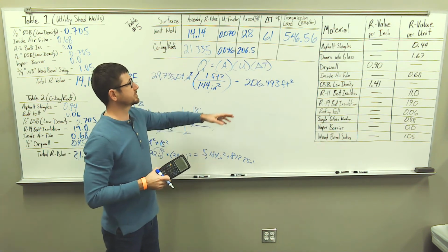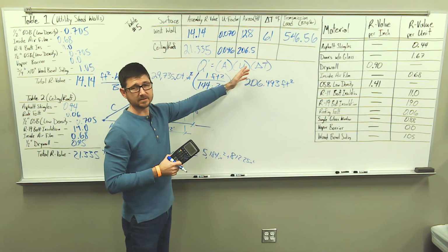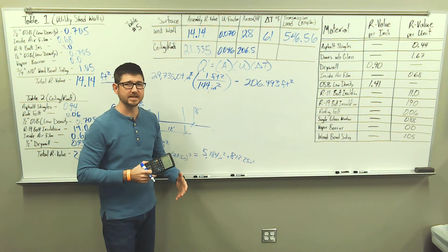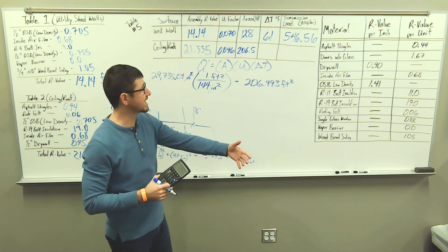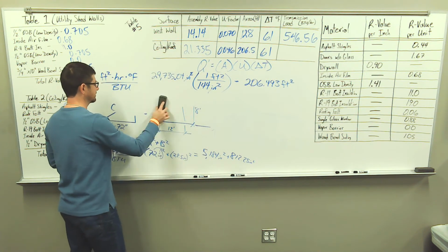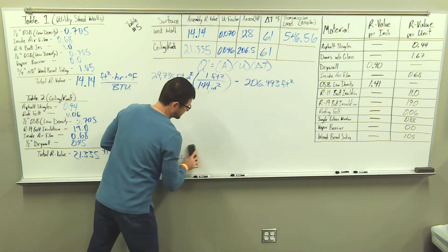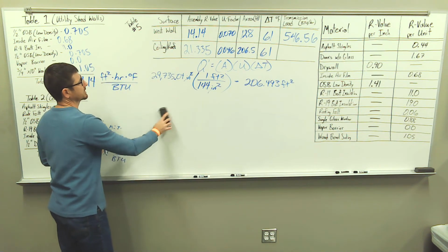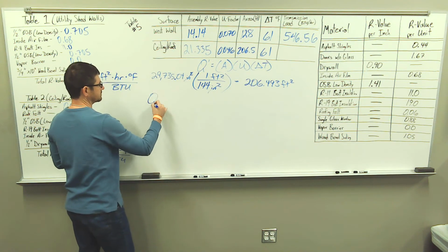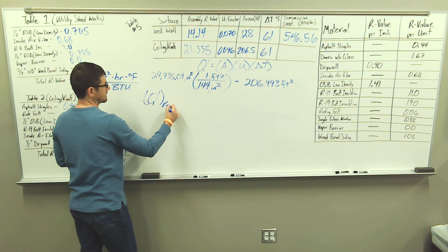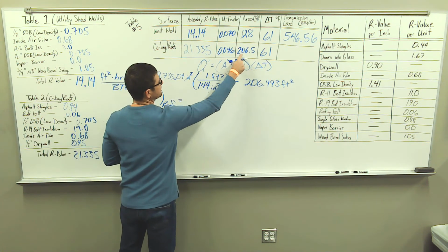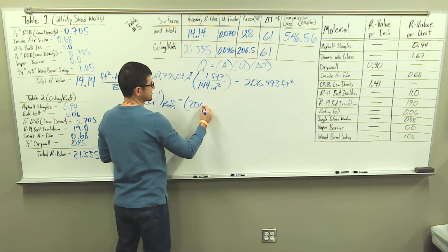All right, our temperature difference between the inside temperature and the outside temperature is still 61. Remember that we have an inside temperature of 70 degrees Fahrenheit, outside temperature of 9, so 61. I'm going to do some erasing here. And we're going to use our equation to calculate the transmission load. So Q prime is equal to A U delta T. So transmission load for my roof: my area, we've calculated that, 206.5.